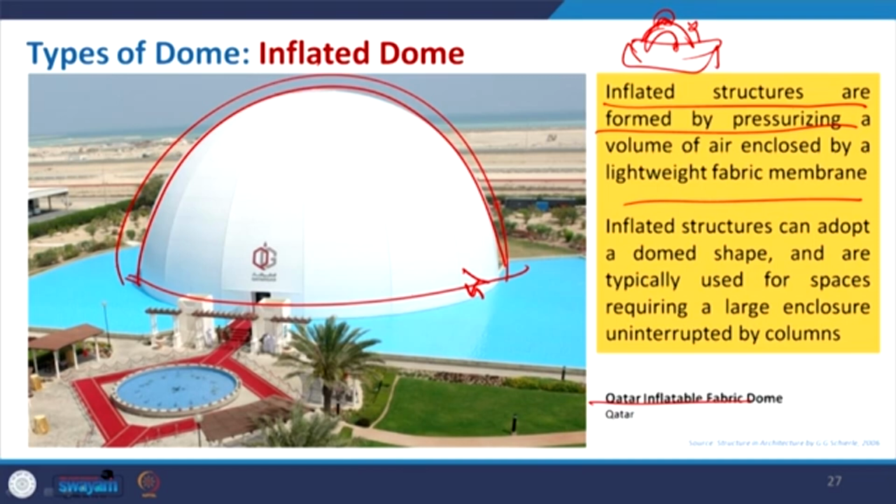This is a very good example, and at low scale, if you use this dome kind of structure, it is again mostly taking compression, and at the bottom hoops you will get some kind of tension. This is also proven to be good for a seismic zone. Instead of having rectangular forms, this dome can be used, even for wind, as it helps to have better air flow, taking the aerodynamics and oscillation into account. So, these kinds of shapes are useful, not only as a roof or decoration for a building, but even for normal low-rise structures as a building. We will discuss this when we discuss structures preferable for disaster-prone areas, and we will come back to this kind of dome form.